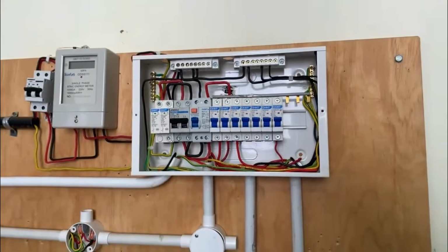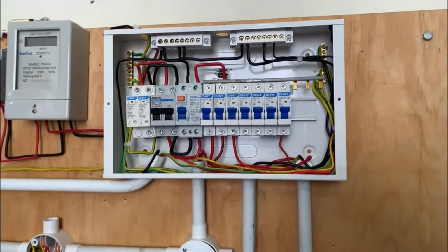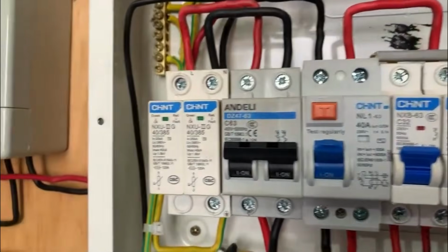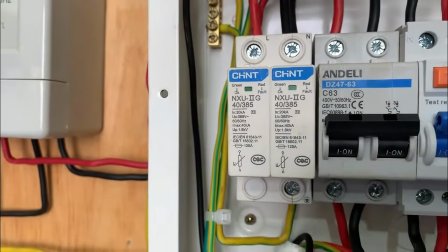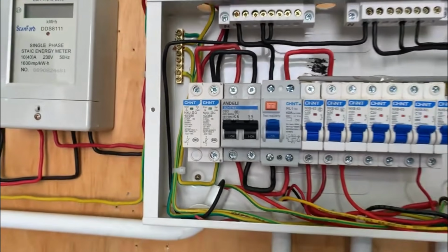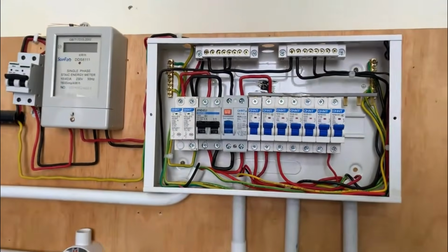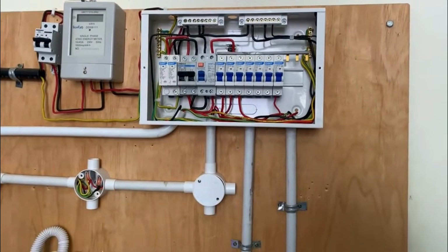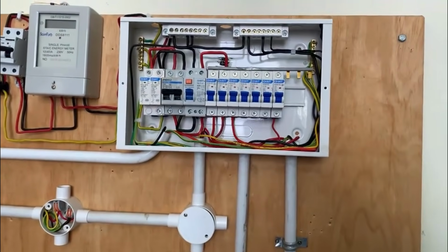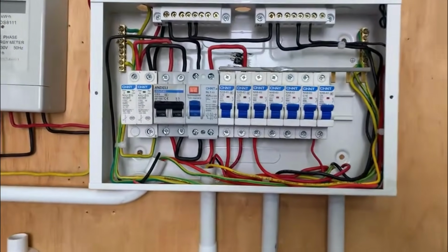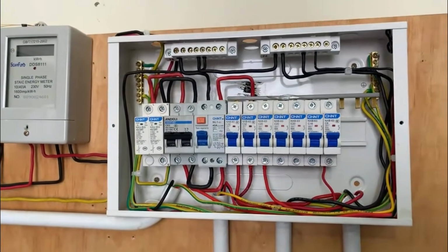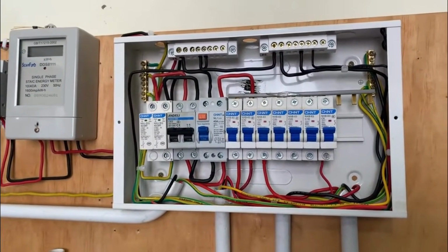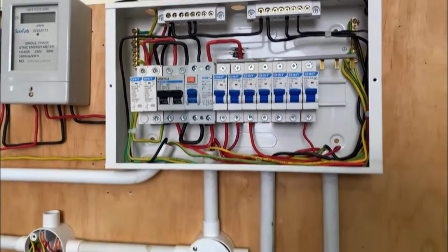We'll talk about that. But first of all, when it comes to MCBs, the protective devices that we have, for instance this one, we have an SPD, a surge protective device. We have the isolator, we also have the RCCB and the MCBs. Loose connections are the main issue that can occur in these MCCB or MCB connections here. As you can see, there are multiple connections.